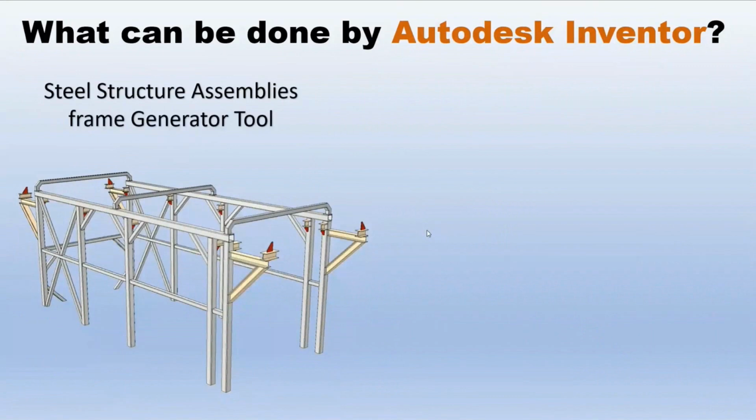You can make a steel structure, a simple steel structure, by using the frame generator tool. The frame generator tool is an included tool inside Autodesk Inventor Professional. So you can build a skeleton for the structure. After that, define the standard of each beam and the size of each beam based on the standard, like Indian standard, European standard.